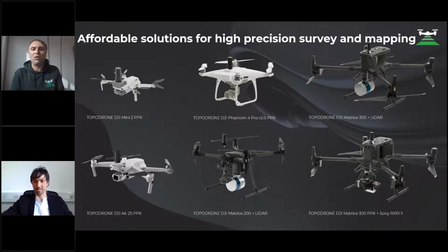I just took a Phantom 4 Pro. And I know from my photogrammetry background that the Phantom 4 Pro has a very good global shutter camera. And after that, I decided, if I combine this global shutter camera together with a GNSS receiver, what results would I have? And finally, as soon as we made the first integration and we made the first results, we received accuracy between 10 and 20 centimeters without using ground control points. And 3 years ago or 5 years ago, it was incredible. It was an outstanding solution. Why?